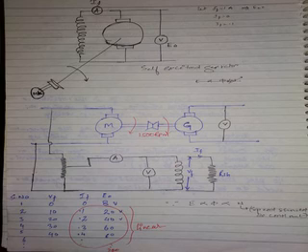So this is what is required to calculate RC. From this, how to calculate the critical resistance? According to the definition, it is the resistance of the field winding above which the machine doesn't build up voltage. Now, the shunt field resistance line will cut OCC at a point P. If you extend this onto this axis, you are getting some voltage, E0.